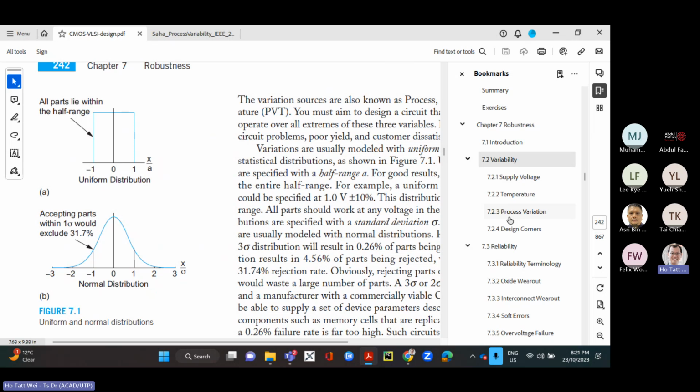like minus something, versus I operate it in Malaysia, where the temperatures are like 30, 35 degrees, versus maybe in an oven or something like that, where it's 100, 200 degrees, or maybe in some industrial furnace where it's 200, 300 degrees Celsius. The performance will be different because temperature influences things like the carrier mobility, number of free carriers, and things like that. Supply voltage influences the strength, the amount of current that is driving.